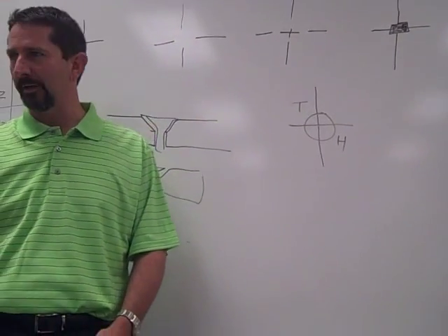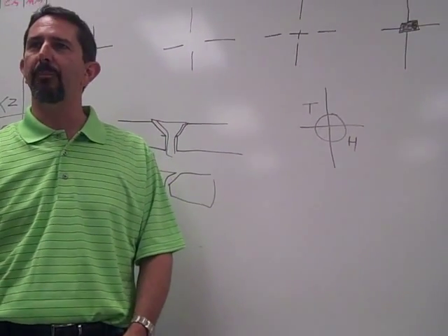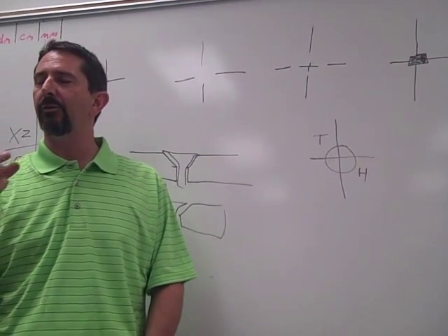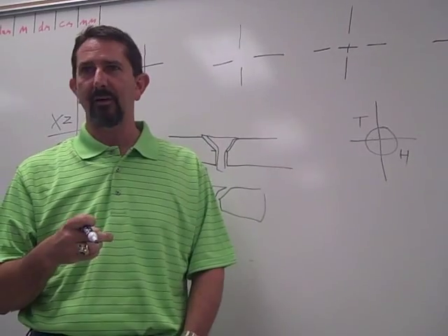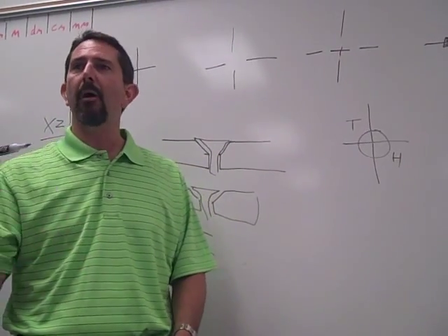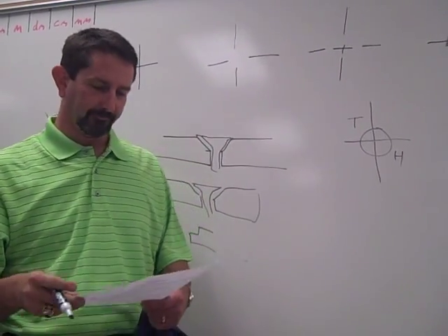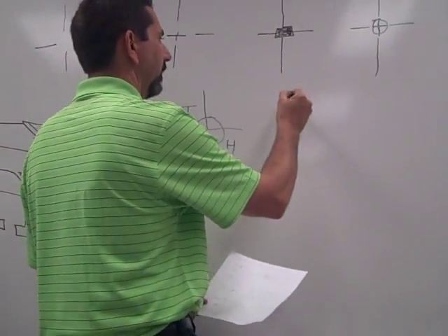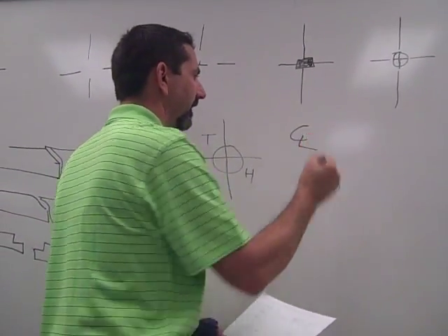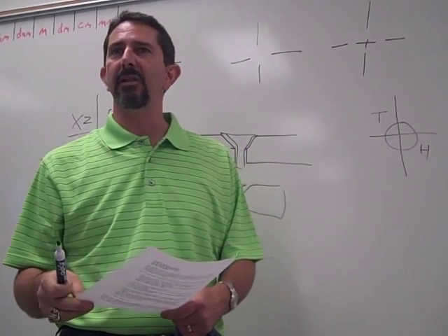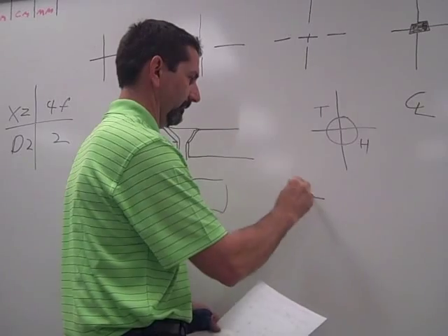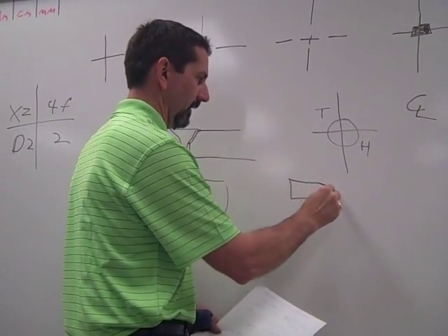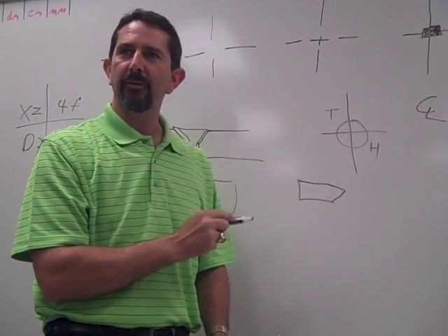TH, tooling hole. Tooling holes are used to pin parts together or into jigs or assemblies to help with the installation process. Very common. Okay, that's how parts are aligned in the tools. Another common symbol, CL, center line. Little flag is for a flag note.